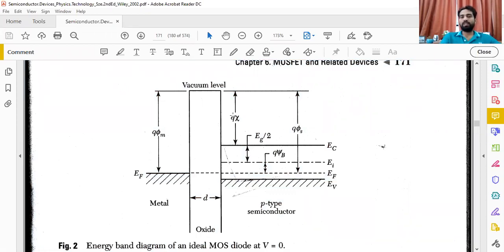We have again a semiconductor material which has layers, like a conducting layer. Here we have a conducting layer, metal has conduction itself. So this conducting layer is here. We have the intermediate Fermi energy level, we have the Fermi energy level, we have the valence band. And we have different energies which represent what the difference will be here. And all of them have been compared with the vacuum level, just for the purpose of understanding these quantum states. And here we have our oxide.